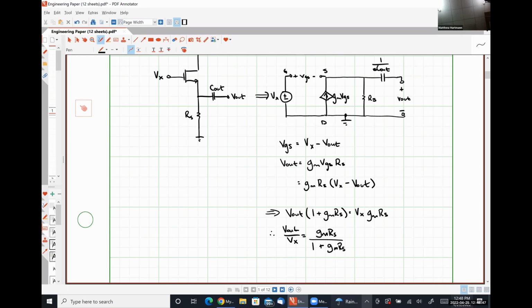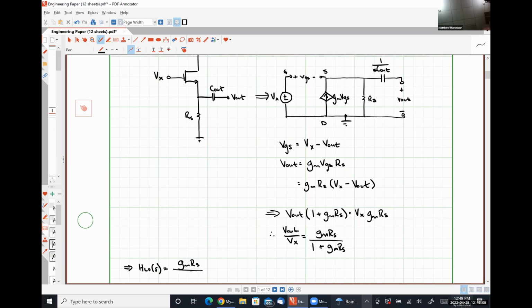So there's no dependency on what we'll plot, this variable S. So from this, our low frequency response is simply gm RS over 1 plus gm RS multiplied by a factor of S RG Cin over 1 plus S (R sig plus RG) times Cin.